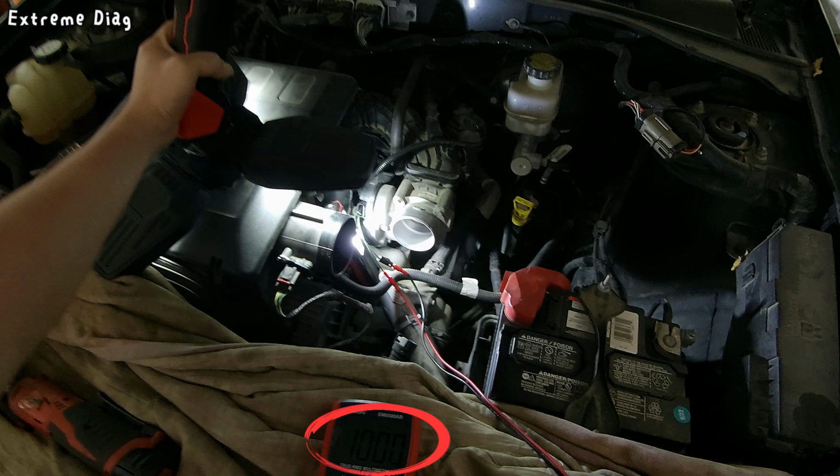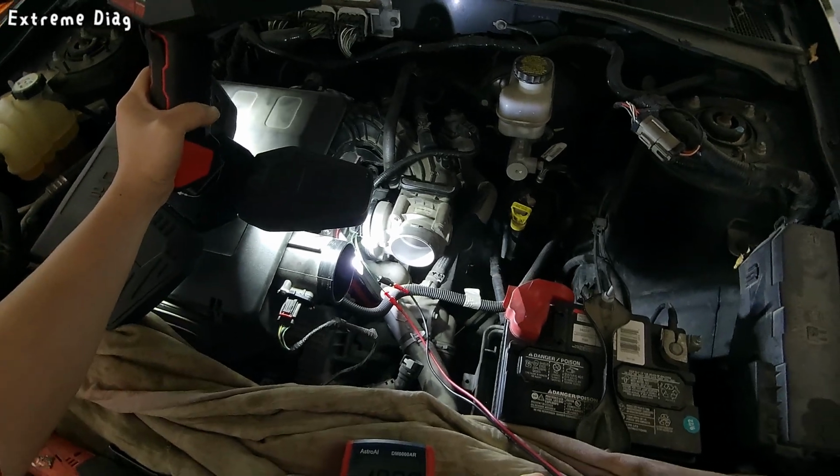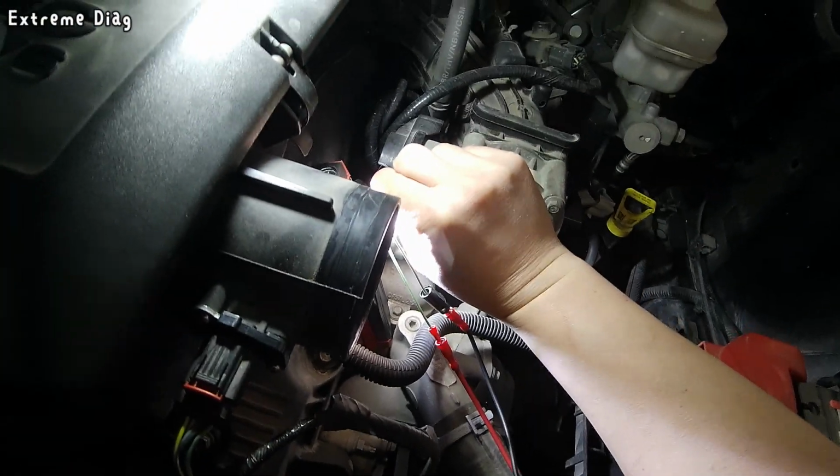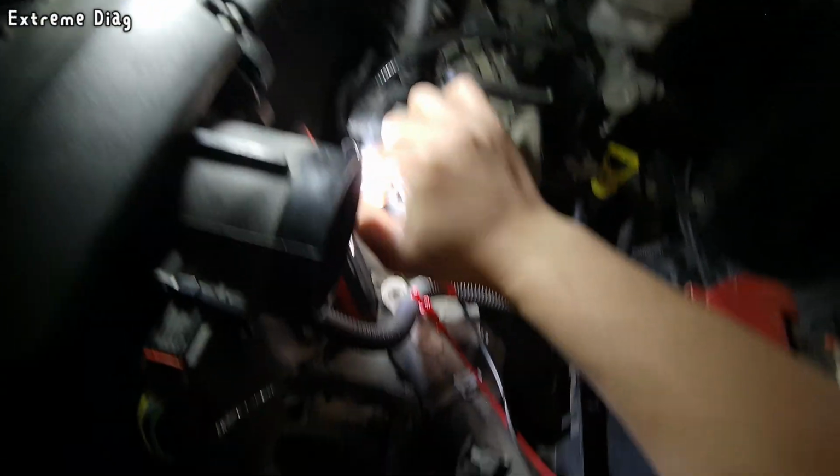Between pins 3 and 5, it reads 10.00. The multimeter automatically switches to the K setting for high resistance. Multiply by 1000, so the resistance is 10,000 ohms.